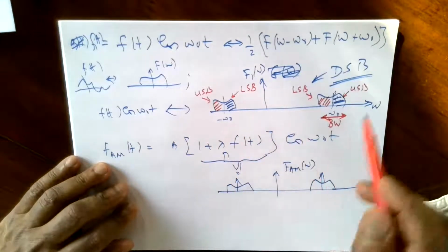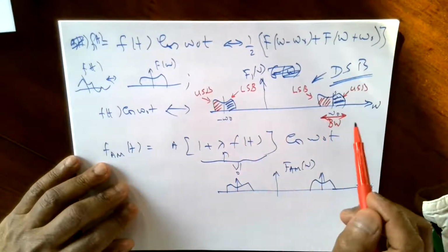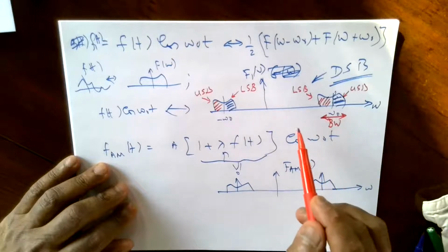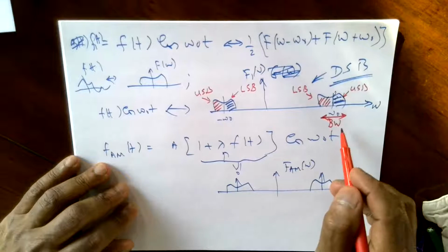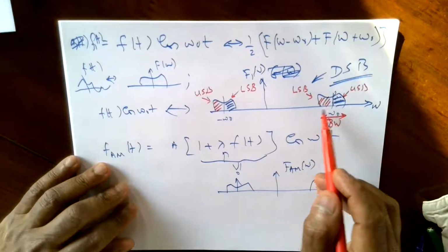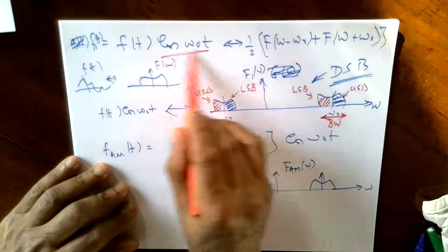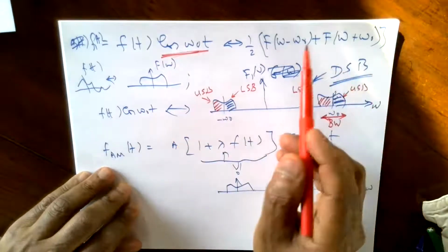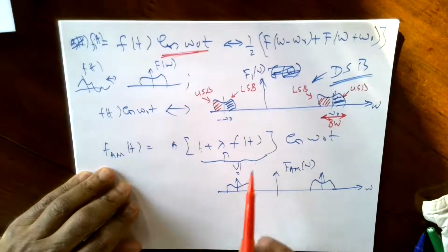So both in amplitude modulation and DSB, we keep both sidebands, the upper sideband and the lower sideband. But that's a penalty. That's a loss in terms of bandwidth, especially if bandwidth is premium, then you are wasting bandwidth here. But the advantage is it's extremely simple to modulate. Either you just multiply by a carrier and transmit, or add a carrier and transmit.